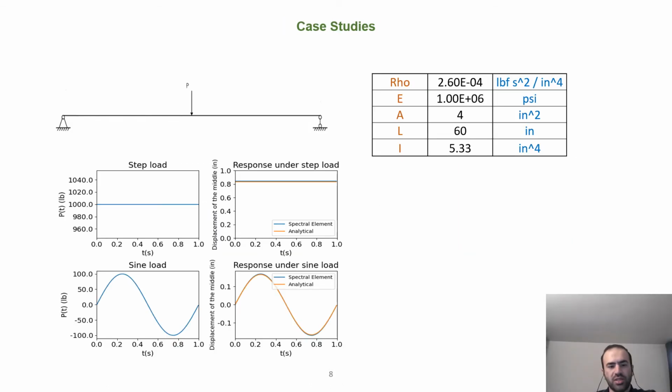In order to investigate the performance of our spectral finite element model, 2 case studies are done. A simply supported beam is modeled with 2 spectral elements, and a concentrated load is applied in the middle, and we're interested in finding the transverse displacement of the middle point.